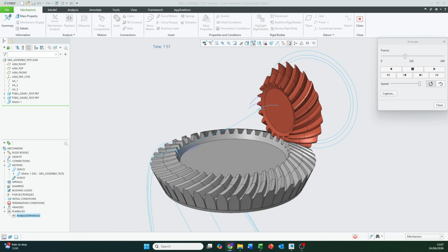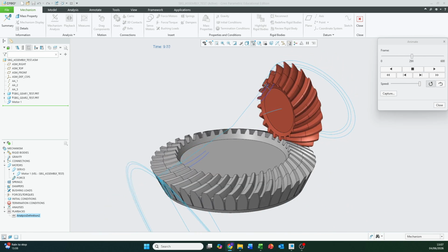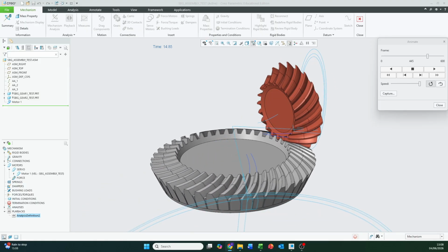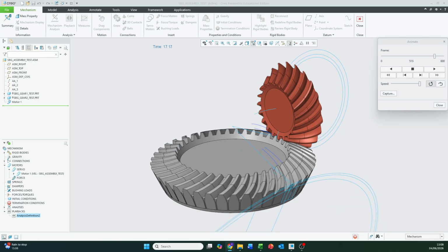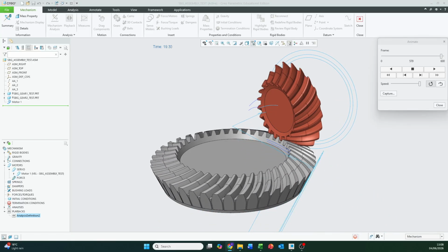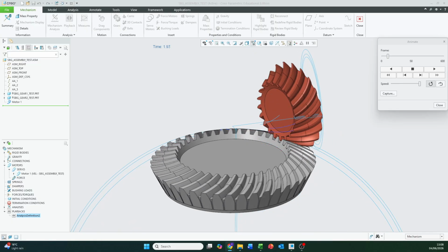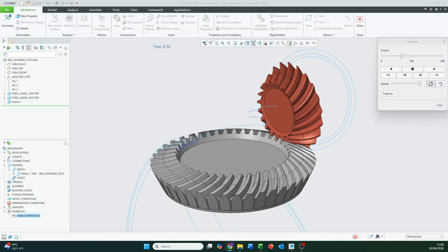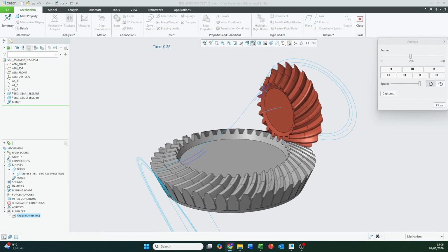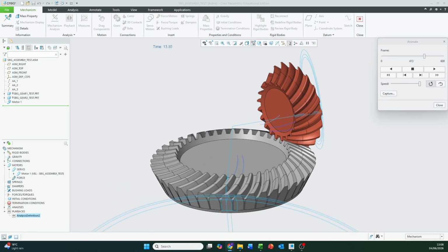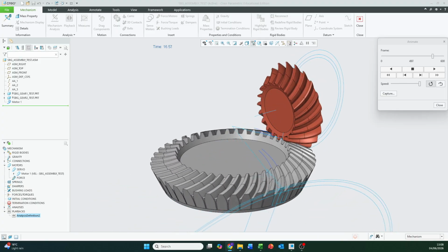We'll still begin by defining the fundamental bevel gear geometry using engineering calculations and relations, and we'll still use a fully parametric workflow to drive the design. However, once we begin creating the tooth geometry, we'll introduce a curved tooth path controlled by a cutter radius and a spiral angle. This additional geometry creates a much more complex tooth form and requires several new modelling techniques compared to the straight bevel gear project.